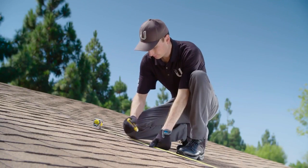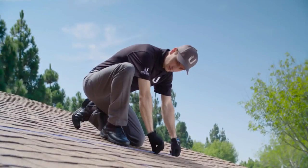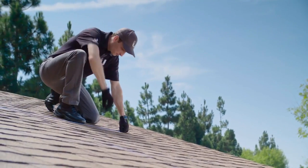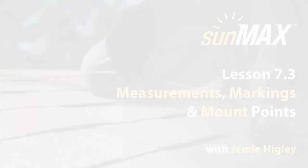To review, based on the final SunMax site design plan, measure and mark lines for roof mounts, taking into consideration the roof requirements for spacing and loading based on the location of the install site. Once finished, place the mounts at intersection points to begin roof penetration and flashing.